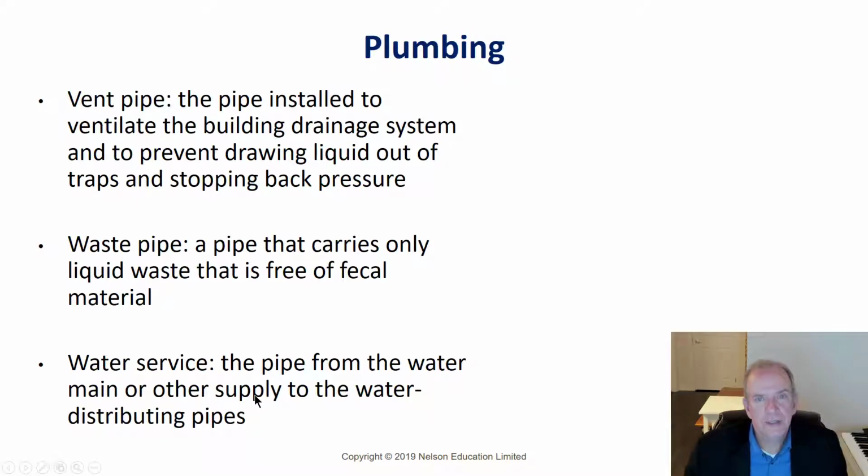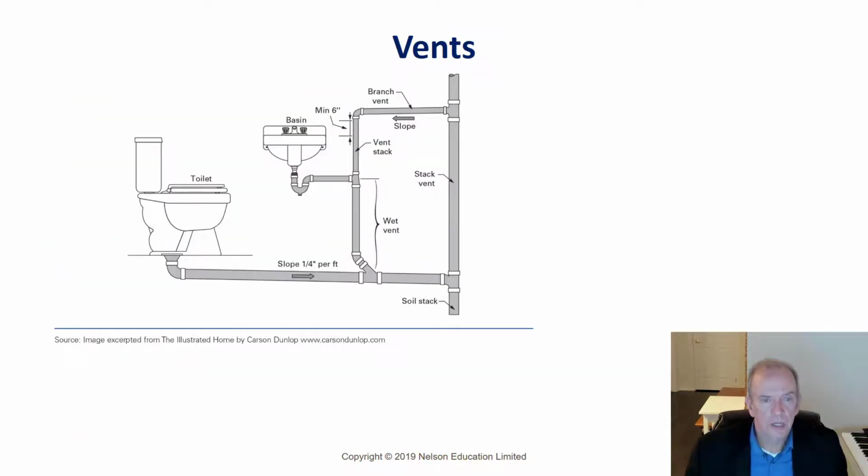Water service, that's the supply line that comes into the house. So we call it the water service. Or the electrical service, that's where the hydro comes into the house, right? So what size is the hydro service? It's a 200 amp service. That's the capacity of your hydro system. The water service is like, what's the size of your water service? Is it 1/2 inch? Is it 3/4 of an inch? Is it 1 inch? Bigger, you're going to have more pressure in the house. You're not going to have where somebody turns on the shower in one spot and in another spot the water goes down. Older houses have 1/2 inch supply lines. And I've got a slide on that in a little bit.